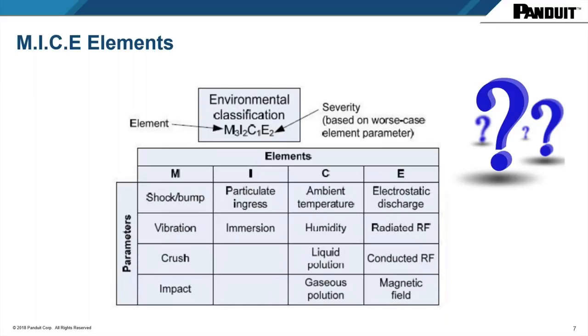When you look at the chemical aspect, what we call climatic, but one way to look at it would be chemical or presence of chemicals. Again, it starts from absence to interim presence to constant presence. And also, it talks about its toxicity. There are a lot of chemicals that will attack the plastics and the TPE and all of the different jacketed material that exist on the connector and all the cable. So you need to be made aware of what type of protection my connector has to withstand, say, in an extreme chemical or a caustic environment that it is being deployed in.